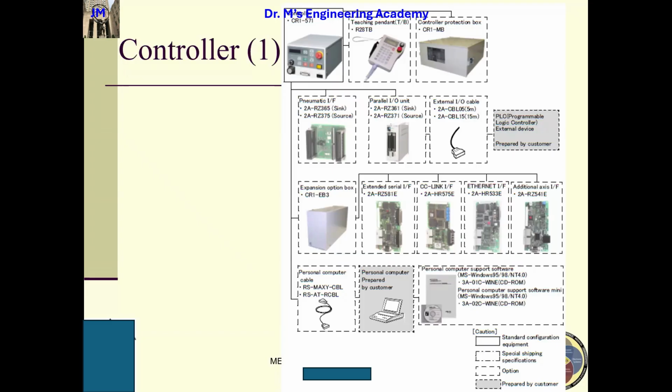Just think about the PLC. We have a PLC unit and a personal computer. On the personal computer we write a ladder diagram, then we download the ladder diagram from our personal computer to the PLC, and then we run it. Conversely, we can upload the programs from the PLC to the personal computer for modification or expansion.